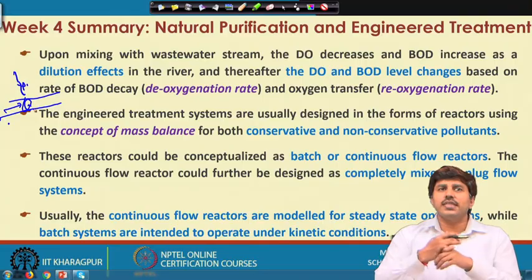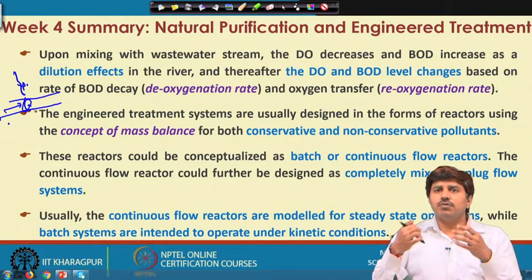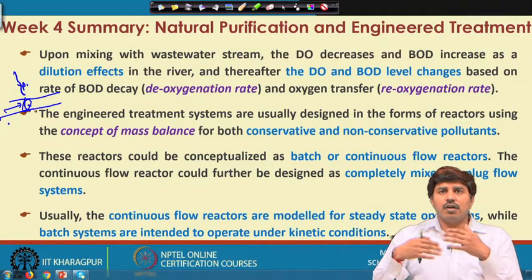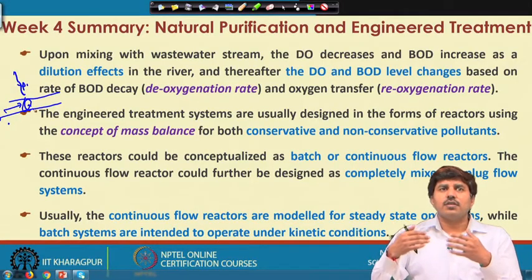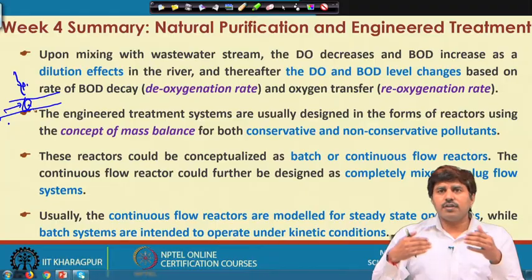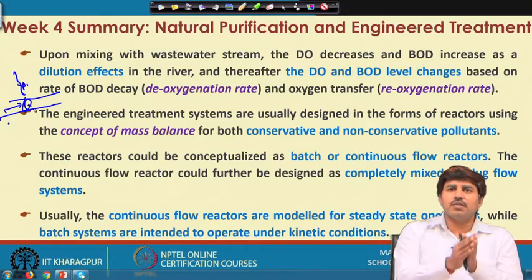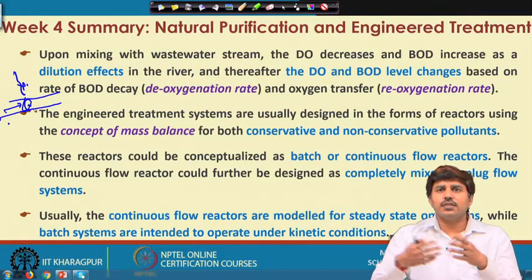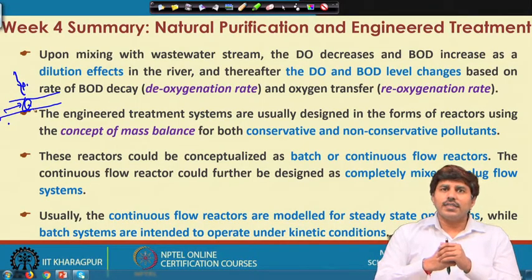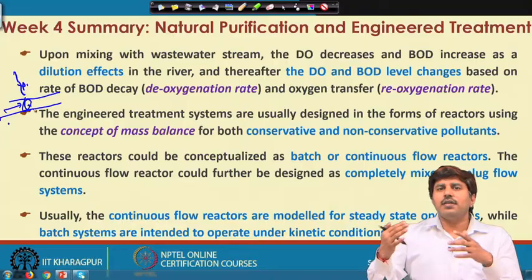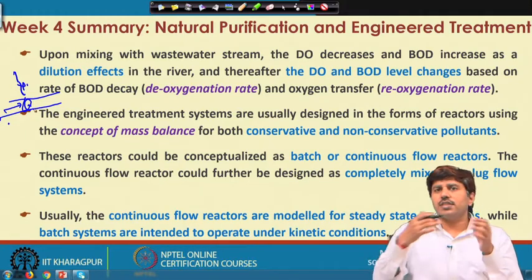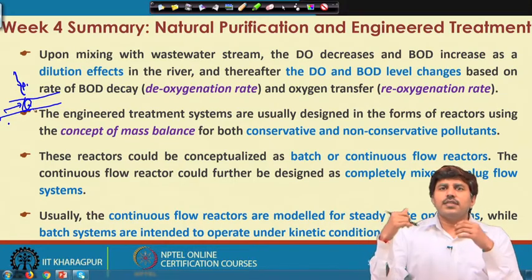From that point forwards the DO and BOD levels will change based on the rate of the BOD decay, because BOD will decrease and oxygen transfer also takes place. From the point of mixing, the BOD is going to decrease slowly, usually by first order decay, whereas the dissolved oxygen levels are more complicated, because the organic matter is decreasing. So, there is a constant decrease in the BOD profile, but